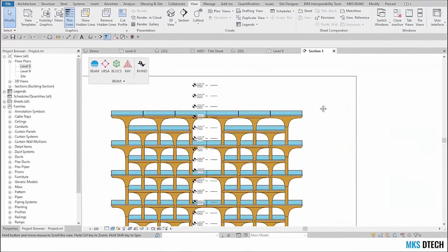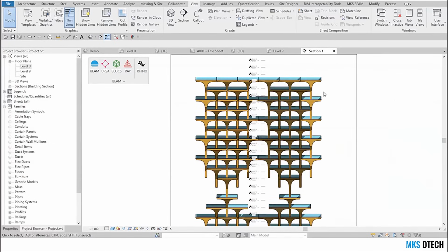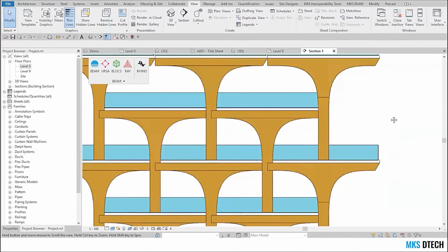It really depends. Yes, as Mikael said, it depends how you model in Rhino, and something really important with BIM is assigning the right category to the objects. So if you are using a wall in Rhino, if you want to assign a proper window or something else, then in Revit you are able to retrieve it and override these categories with the visibility settings. That's really important when we are working with 2D plans.